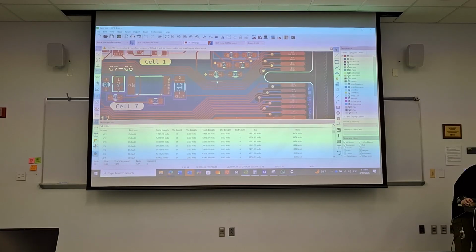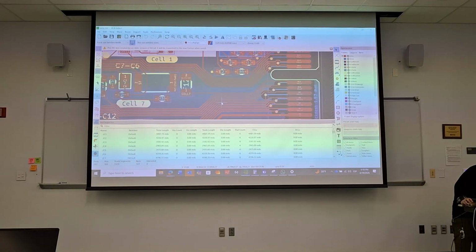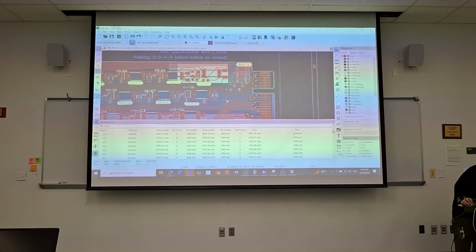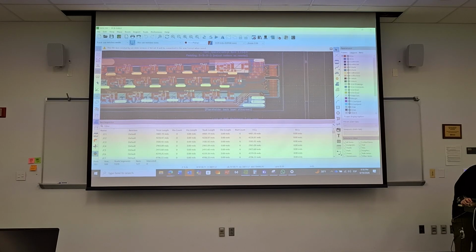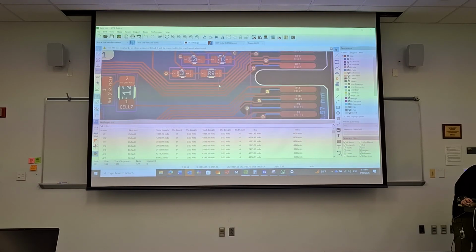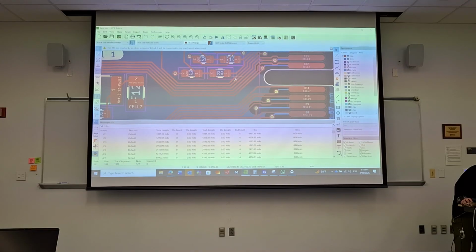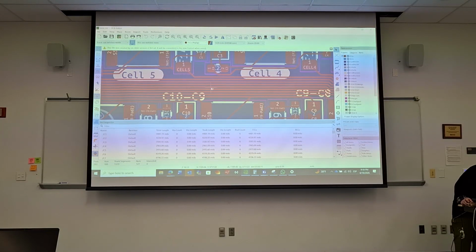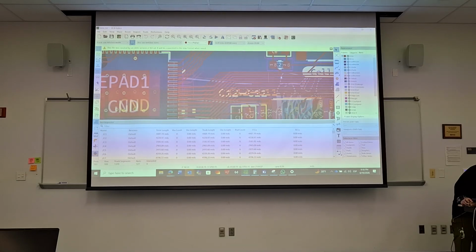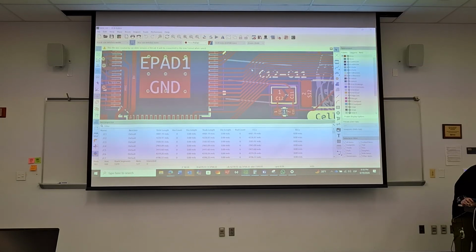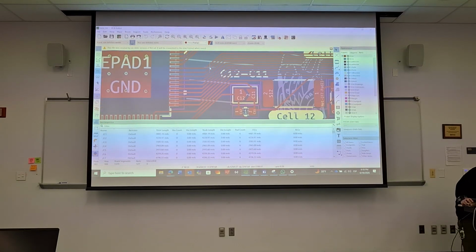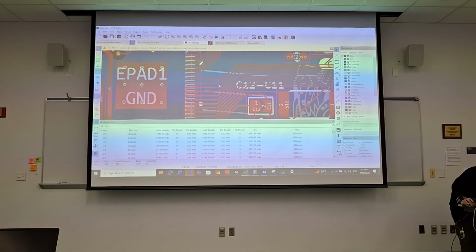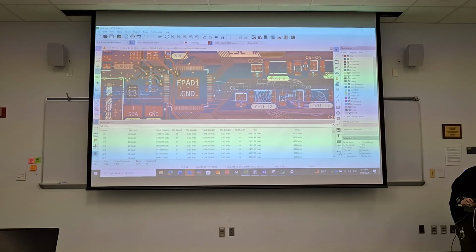Sure, it's very tight and it's a lot of crosstalk, so I would try to increase the footprint of this so that you get more room. But the redeeming grace is that we have solid ground all throughout. So even though these traces are huge, it at least has a short enough return current because your copper is immediately below.